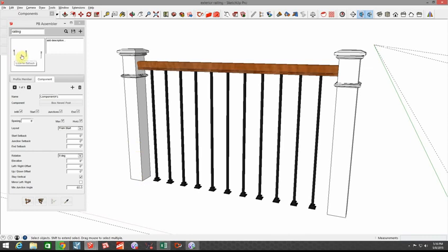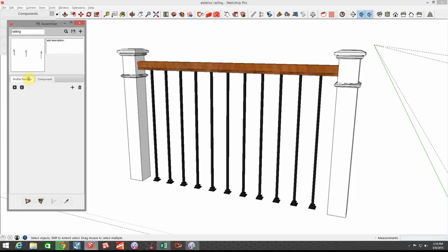Okay, so you can see in the window here that I've got newel posts that are spaced out at 8 foot centers, and I want one at the end and the start, and the junctions and the infills as I go around.